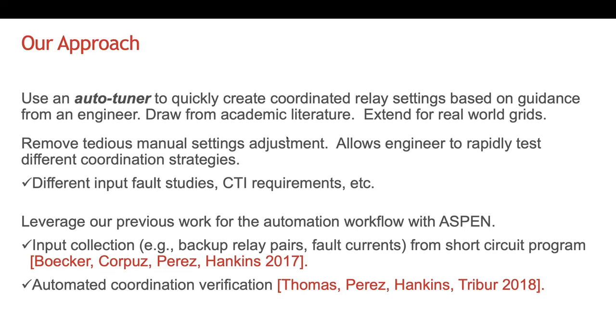And so we remove the tedious manual settings adjustment, and allow the engineer to rapidly test different coordination strategies. That may be different CTI requirements, that may be different fault regimens that they want to ensure coordination for. And this is really based on the automation foundation that we laid in interacting with ASPEN through PowerScript and then now OlxAPI.